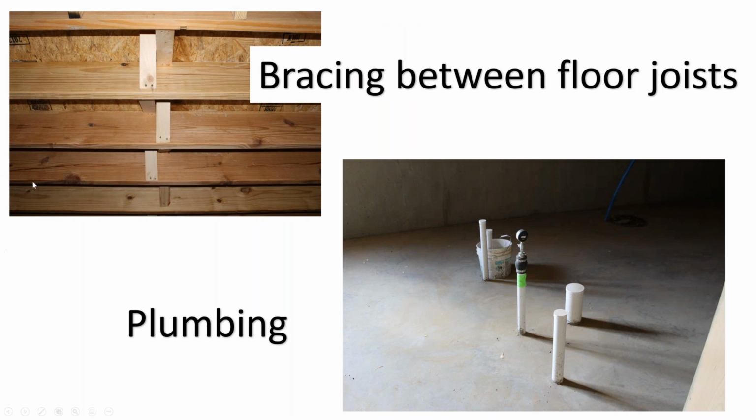Bracing between the floors, that's what these little pieces are right here. And as you walk on a floor, sometimes you can feel it move and shift. Oftentimes you can come back in and re-support it, or you'll notice that these have come loose and they're dangling. These are to keep those joists from moving. So they're keeping it sturdy. So if you go down into a basement of a house and you see them kind of hanging, most likely it moves a little bit up above it and just needs to be resecured.